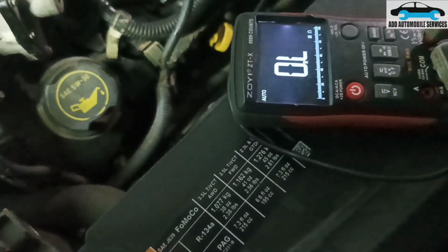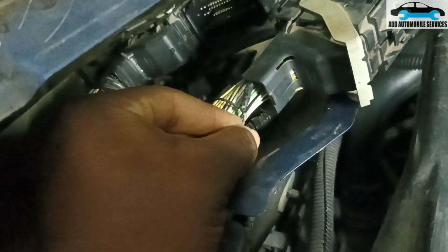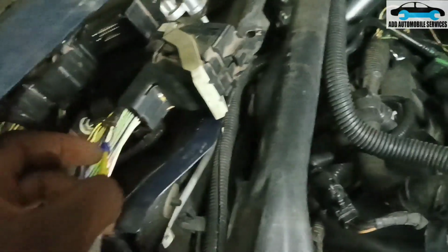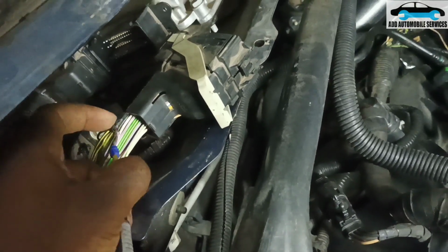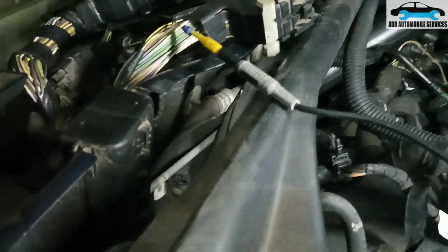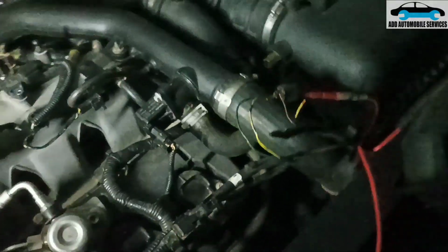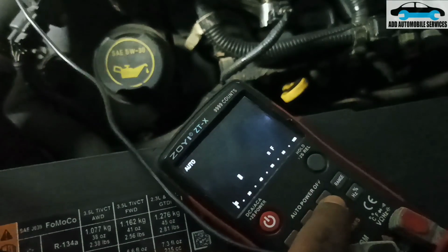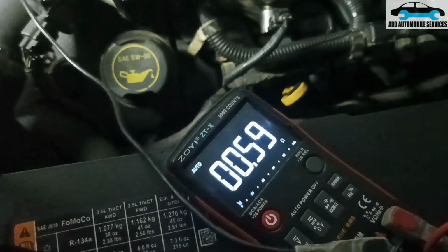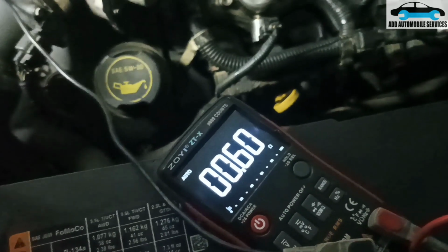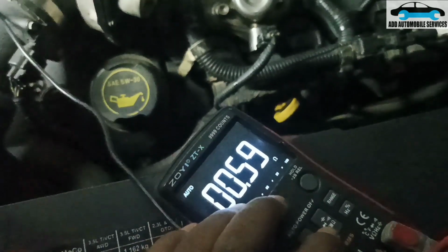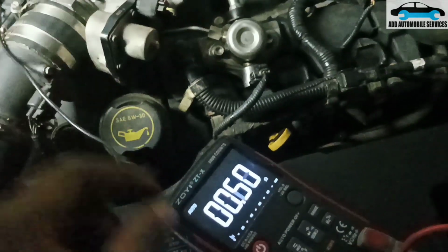So now what I'll do is, I know the 5 volts point, which is this one, so I'll probe it and do my continuity testing and see what I'll be getting. And even apart from the continuity testing, I'll also do a resistance test and see, to make sure that that's the exact one. So now after connecting it, you can see the beeping. So what I'll do is I'll change it to resistance and see 0.6 or 0.7 ohms, which is not much. So what I'll do is I'll cut the wire and join it and see.